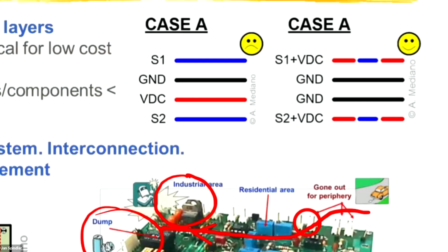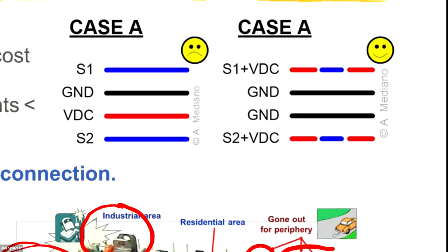This is a very complex topic, but considering this plot, the idea is that you are using a plane for the VCC line, for example, 3 volts. For the signals in layer 4, the layer that is S2, these signals will find the return path in the power supply plane. So you will have a lot of noise in this power supply from the signals in layer 4. So this is very dangerous.